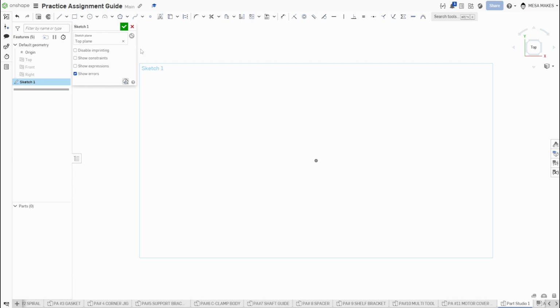So in our drawing, I have a dimension of side to side of a hexagon. So we'll do a circle inside, inscribed. If we take a look, that circle is inside. So what I need to do, in my drawing, I have that point. If I go out to the right from the origin, I get a point. If I go straight up from the origin, my points are to the side and I get a flat top. So I want flat sides. So we're going to click there. We're going to say we want 6 sides to our polygon, and that needs to be 1.5 wide.